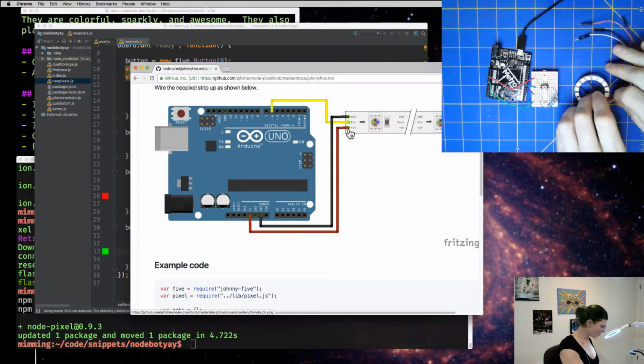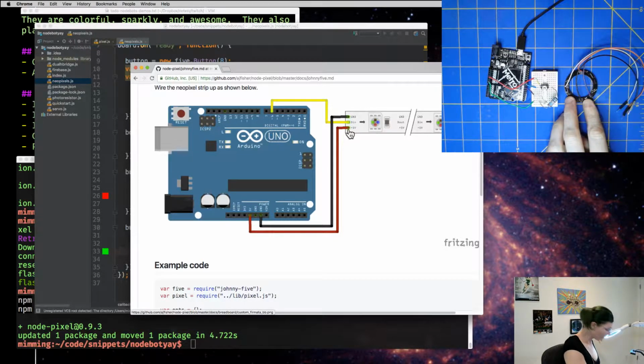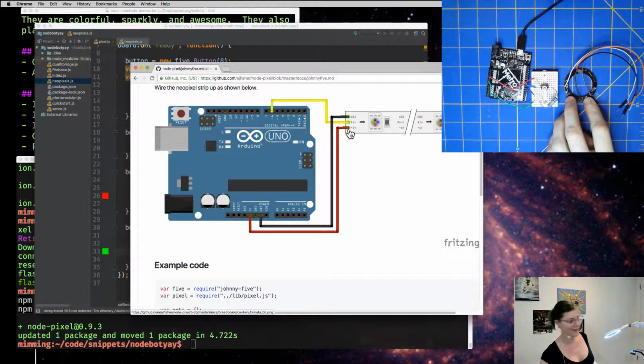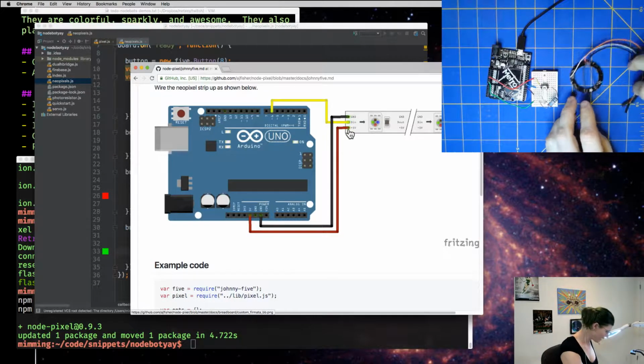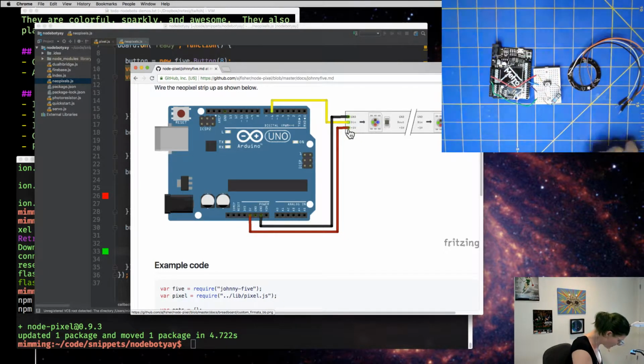We actually have 4 wires in our ring. The pins are all labeled on the back of the ring. The difference here is that in addition to data in, we have a data out. So if we wanted to chain a bunch of them together, we would use the data out pin. We'll ignore it for now. So let's unplug our Arduino and wire it up.